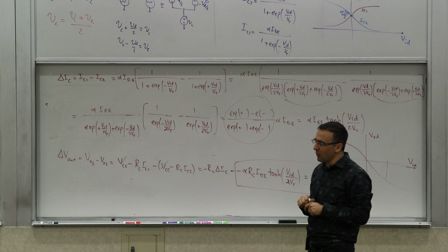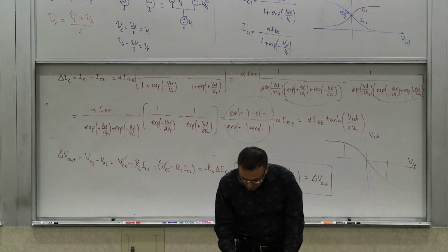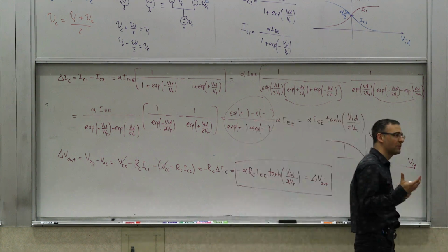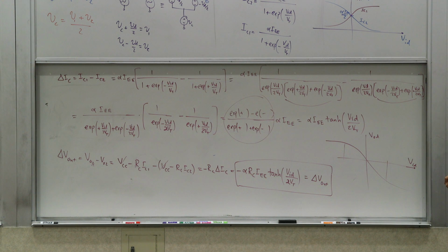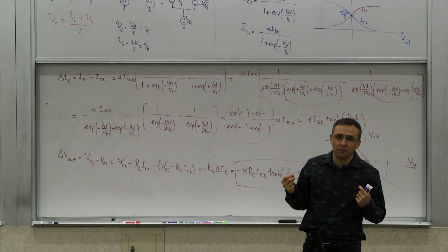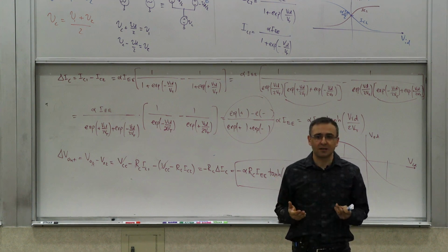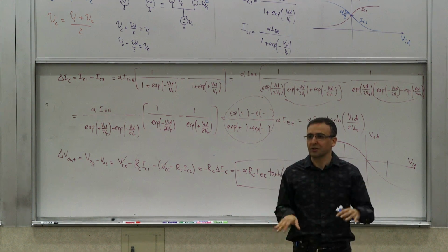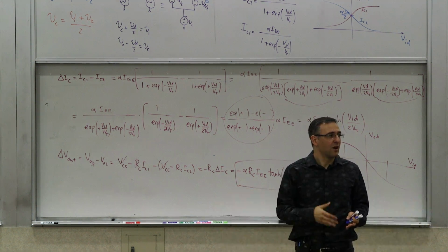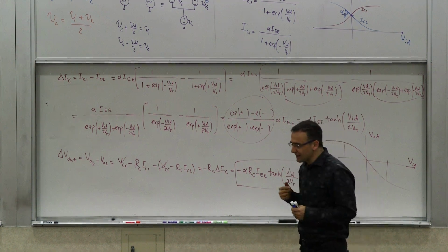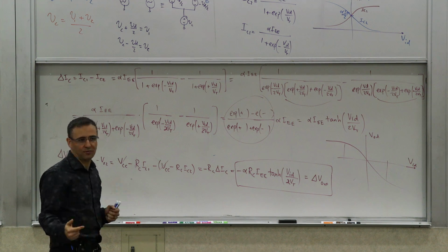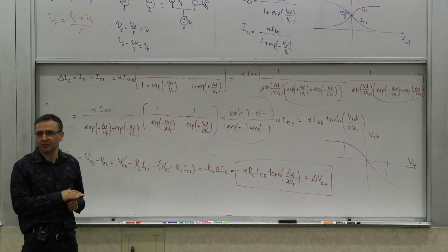Okay? Now, what we'll do next is to look at this large signal behavior and look at the small signal equivalent of this circuit. And you'll see different ways to analyze it and simplify it to think about these differential stages. And these differential stages are very critical to a lot of design for a variety of reasons. One is that because you have the differential signaling and suppression of the common mode signal, you can actually get a lot less sensitivity. And this is important if you are putting a lot of stuff very close to each other on a chip.